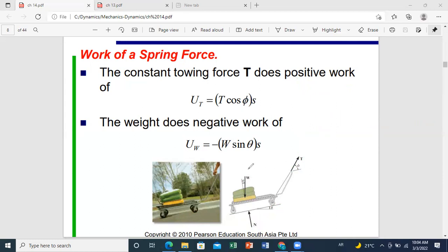First, you can say it's a normal force. Let me project it along motion and then multiply by the displacement. So you can say that your weight here is vertical, okay? And therefore, it's not perpendicular to motion. So it has two components, one perpendicular to motion, one parallel to motion. This is the line of action of the weight. It's a vertical line.